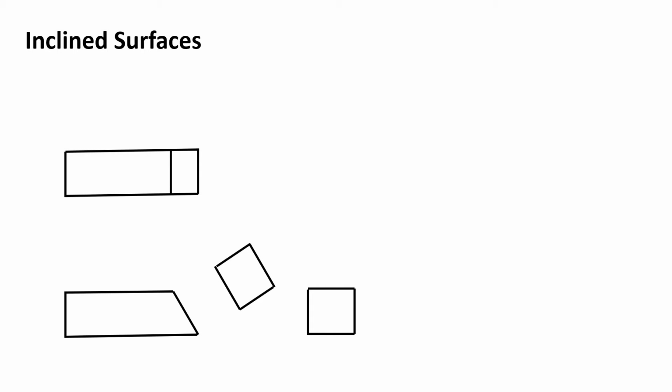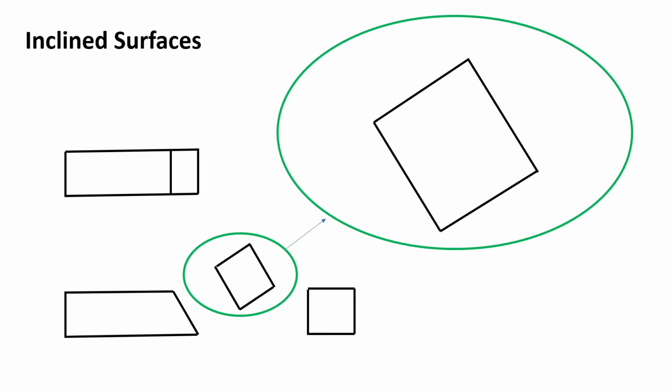Even with this very simple example, we can see the importance of explaining an inclined surface by means of an auxiliary view. The final drawing of the inclined surface looks completely different from the information provided in the three main views. We have essentially taken this line and this line to accurately describe what the angled surface actually looks like.